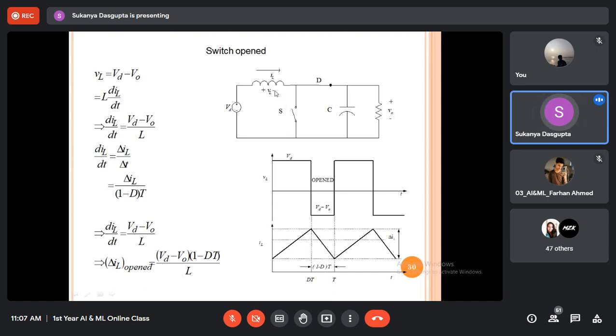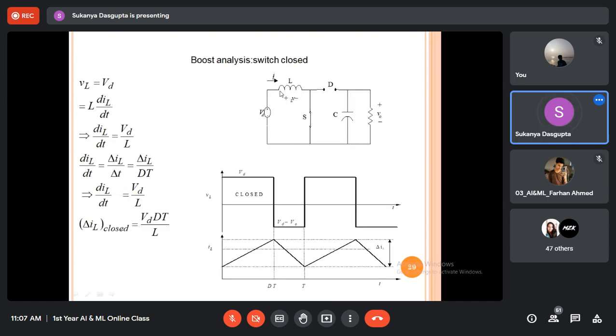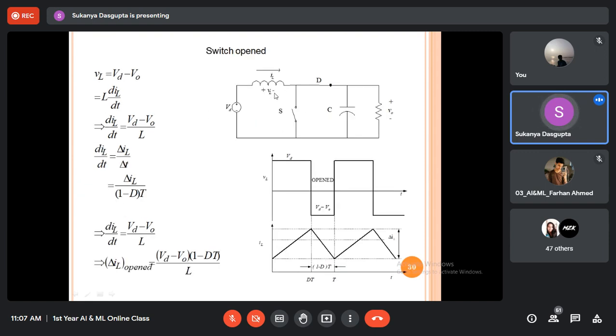So this is now positive. Previously, this side was negative polarity. Look at the circuit. This side was negative, but now this side will be positive. So since it's now positive, current will be flowing like this. So the anode of the diode will be now positive. So the diode will be forward biased. So current will be flowing like this through the load circuit.